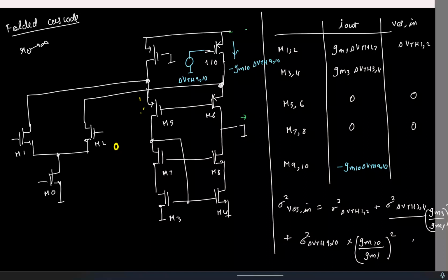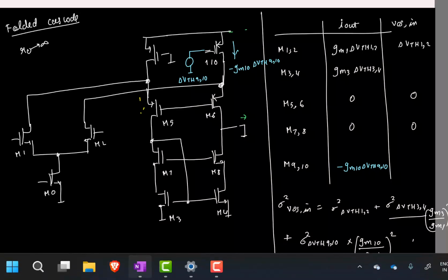So if you have an NMOS input stage, the common mode for the input can be at 0. At VDD. Sorry, I made a mistake. Yeah, you're right. For NMOS, the common mode can be at VDD. Similarly, for the PMOS, the common mode can be at 0. So that's the only advantage with folded cascode, right? If you don't want a case like that, you are better off using telescopic cascode, because this is adding more noise and more offset. Okay. So let's stop here.